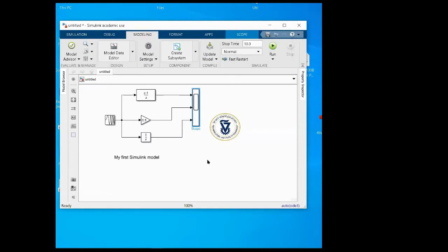Now I also have a question. I do everything as you did, but when I hit run, it doesn't do anything. But when I just click the scope, it opens the graph. Yeah, because when you press run, it just runs the simulation. It means that Matlab does all this calculation, but you cannot see anything because it works inside Matlab, inside Simulink. Oh, I also cannot see it. Let me show. I press this button, nothing happened. I cannot see anything. Okay.